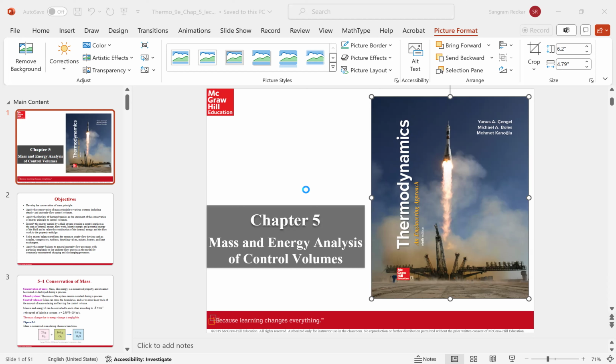Now I want you to imagine the space shuttle. Have you noticed that at the bottom of the space shuttle, they have nozzles, but they are diverging? Why? Let me tell you the reason for that. When the gases are coming out of the space shuttle, they come out at a speed higher than the speed of sound. A converging nozzle can increase the velocity when the velocity is below the sound barrier.